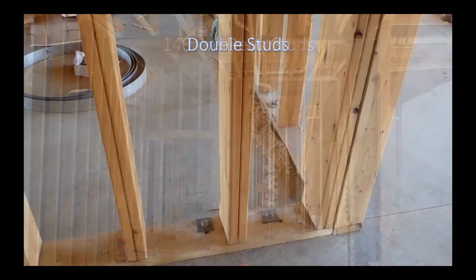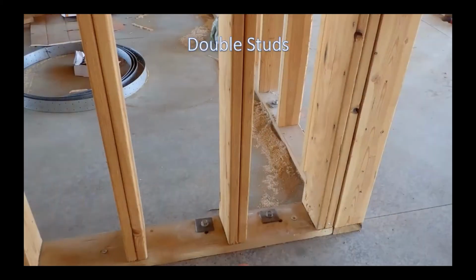They're not afraid of using double studs either. As you go up six stories, that's quite a lot of compression load coming down. There's a lot of double studs being used everywhere that we see where it's appropriate.